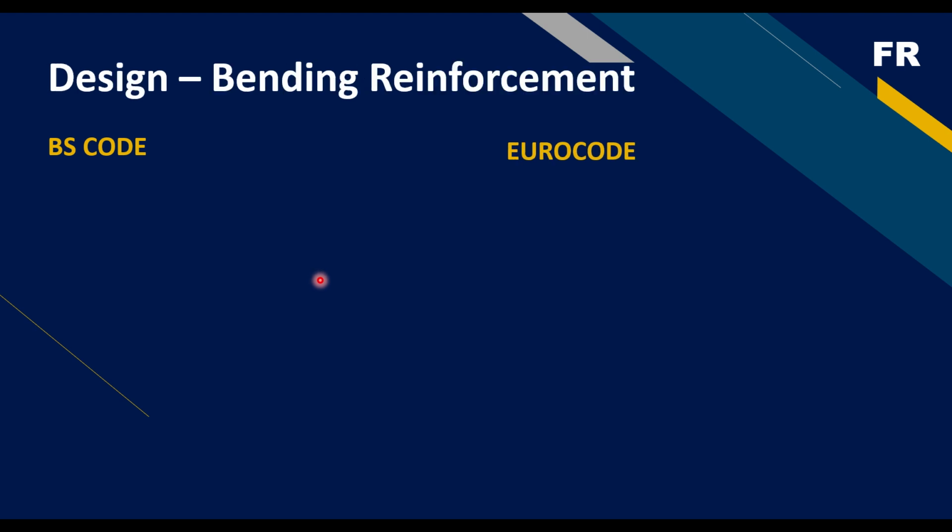So the next thing is to design. We are going to be looking at the bending reinforcement. In slab design, we understand that we try as much as possible not to apply concentrated load on the slab. So when you avoid application of concentrated load on the slab, you don't need to check for shear reinforcement. The only thing you need to check for is the bending reinforcement. So bending reinforcement, according to the BS code, is quite straightforward.